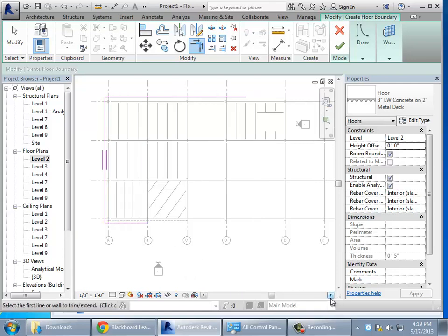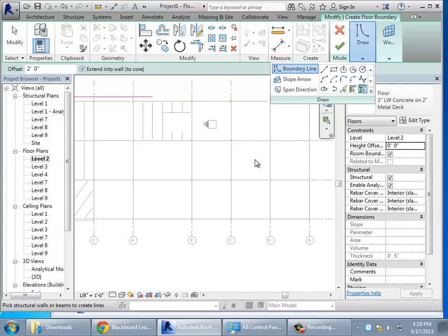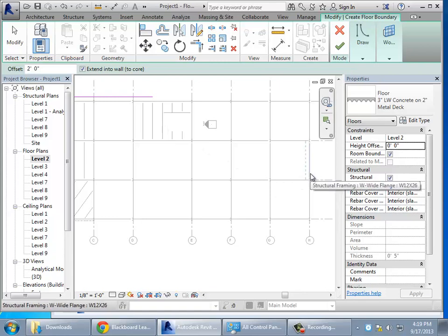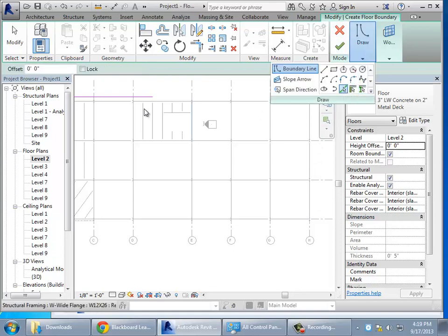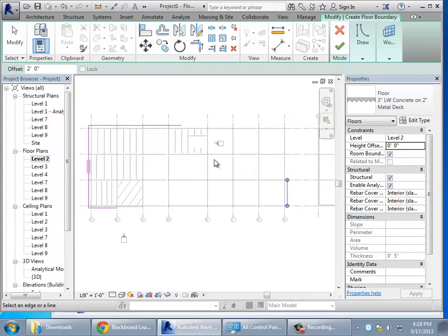Round it all out. I'll put one on the other side. Again, I'll offset over here. Let me do that, but I'm not going to worry about it too much. Do it that side. A very common thing is that rather than drawing all the lines independently, it may be easier to draw just a few lines to define things. We go through and trim to create the boundary. As opposed to drawing that as 15 different individual line segments, it probably is determined by one boundary you want to measure off of. So it's okay to do that.